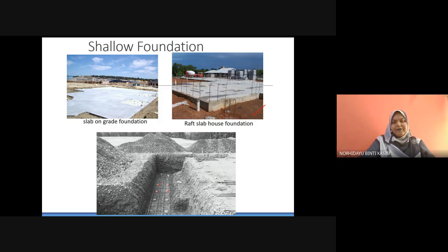Okay, this one I think is the reinforcement bar. They arrange it in the hole, following the drawing, and after that they pour concrete, or sometimes, if necessary, they put a formwork, and finally they concrete the structure. So that is how they construct a shallow foundation in construction.